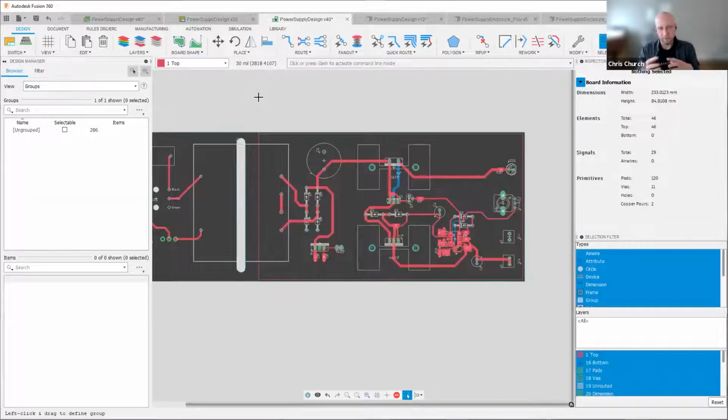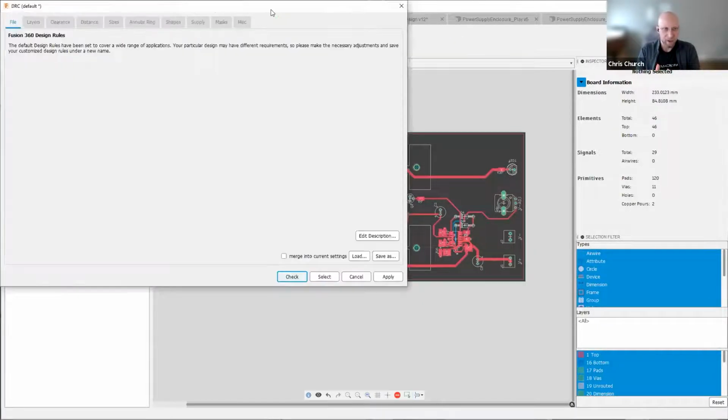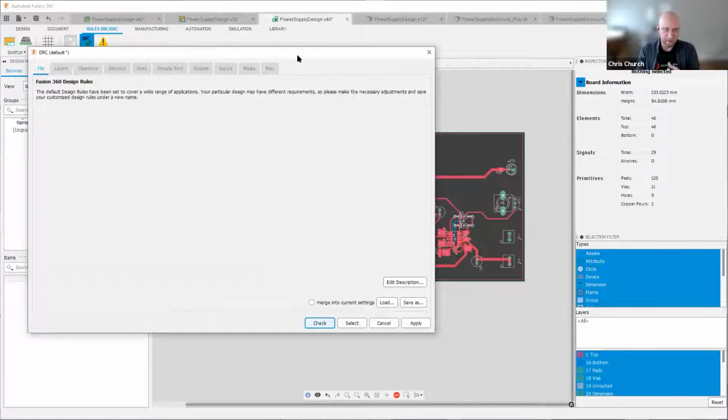So thinking from the perspective of design rules, every manufacturer out there, when we're talking about the PCB and even into the mechanical assembly part of it, they're going to have some number of design rules for you. Typically, those will be posted on their website. But with MacroFab, we actually give you the design rule files for Fusion 360 ready to go. I'll actually post a link right here in the chat in GitHub. And then you can just load these design rules for your design, and it will tell you where you're within certain price points or making an unmanufacturable design. It can give you that feedback instantaneously.